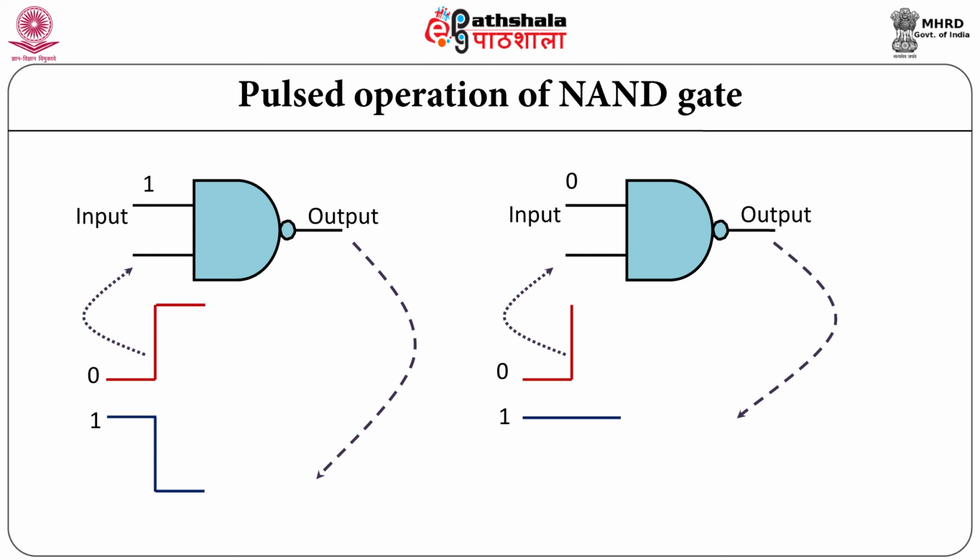It is observed that the gate which has one of the inputs as logic 1 allows the waveform to pass, but in a complemented form. Thus, the first NAND gate acts like an enable gate, whereas when one of the inputs is low, the square wave does not reach the output. Therefore, the output is low only when both the inputs are at logic high.